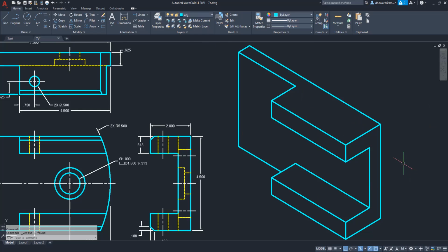So let's do that. The bevels are through 13/16 in size, equal size leg. So if I go to the corner and I pull down in this direction 13/16, it's just 3/16. 3/16 of an inch, which happens to be 0.188. Okay, and then I move over this away. I can mark, and I'll just kind of drag it off the edge. I can mark the chamfer.